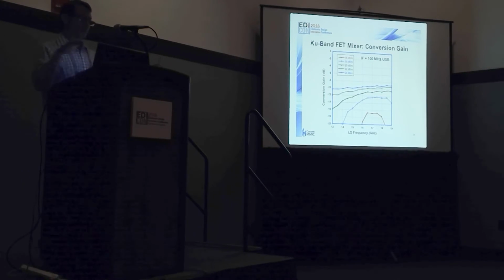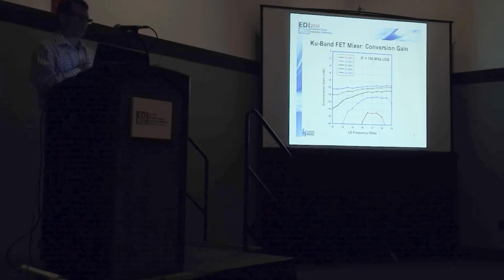But we do see that very nice flat response as we drive it hard enough. We drove this up to 24 dBm. I would have liked to have gone higher, but our lab equipment kind of stopped there. Generating power at those frequencies in the lab can always be a challenge. I think if you could drive this a little bit harder, maybe up to 27 dBm, you might get flat 8.5, 9 dB conversion loss across the band. But we certainly have not